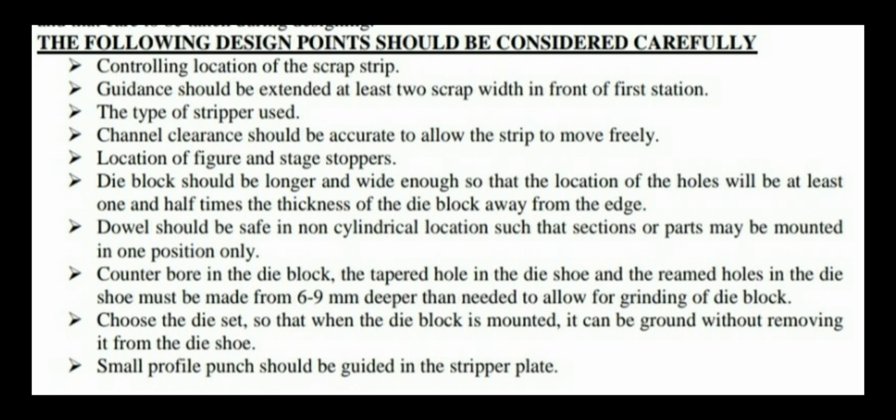Guidance should be extended at least 2 scrap widths in front of the first station. The type of stripper used is also very important in press tool design. Channel clearance should be accurate to allow the strip to move freely. The location of finger and stage stoppers is also important.